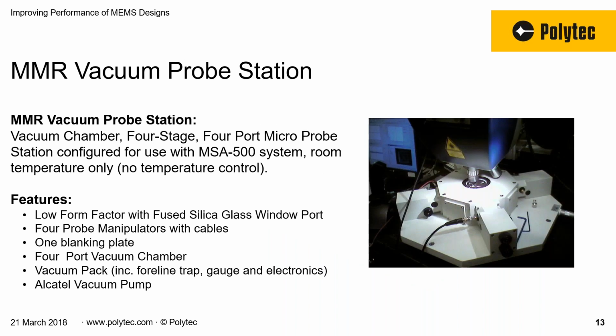So one question that gets brought up is, can we do measurements in a vacuum chamber? And the answer is yes. We've actually configured this system with vacuum chambers. A lot of devices are designed to work in vacuum because of the damping from air. So we're able to target our measurement laser beam through the glass in a vacuum chamber and measure down into it. You can see the example here.